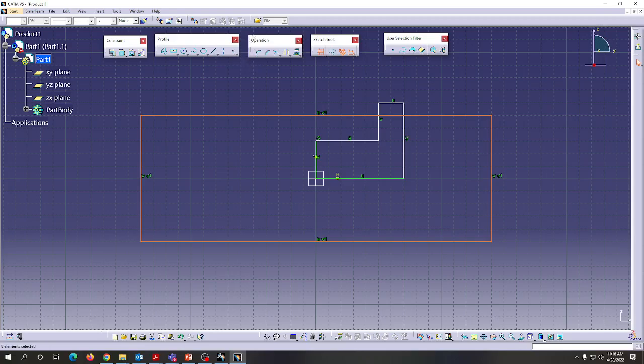And this is the operation toolbar. If you want to do any curvature, this is the corner toolbar. This is for the smooth curve or fillet, and this is the chamfer toolbar. And this is one of the important options called the trim option. If you click trim over here, so many other options are available. Mostly we will use only this kind of quick trim, so direct trim can be done with the help of this one. And this is the mirror toolbar.